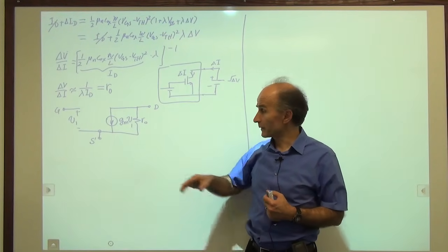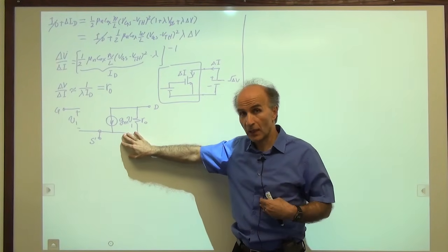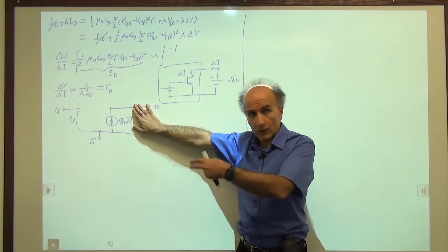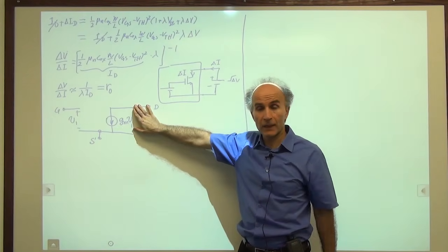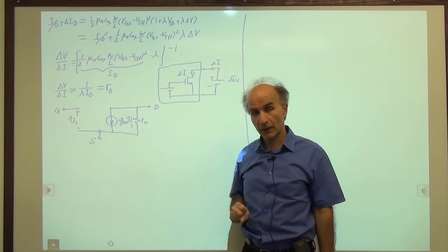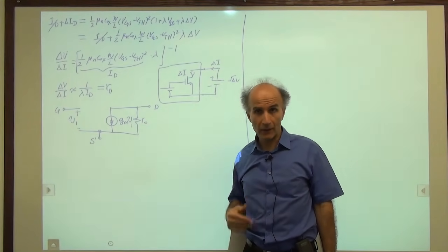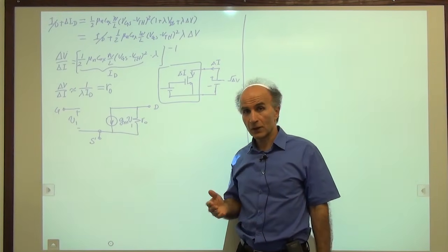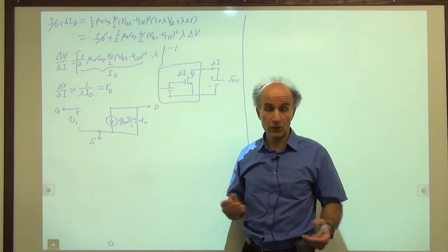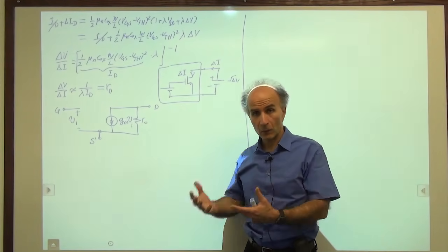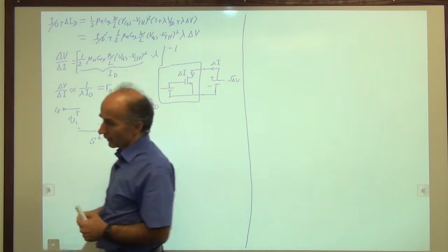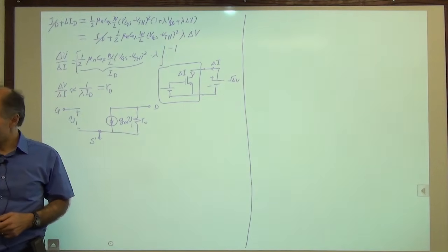And when it comes to the small signal model, our first reaction is to neglect channel length modulation and proceed. We go ahead to the calculations for the circuit, whatever is of interest to us, and then see if the results are sensible. If not, we come back and include channel length modulation. Sometimes it takes experience, a lot of practice, to see under what conditions channel length modulation is negligible or not. And that's what engineering is about. You have to develop that sense of when we can make what approximation. All right, so based on this model, now we can analyze various circuits.